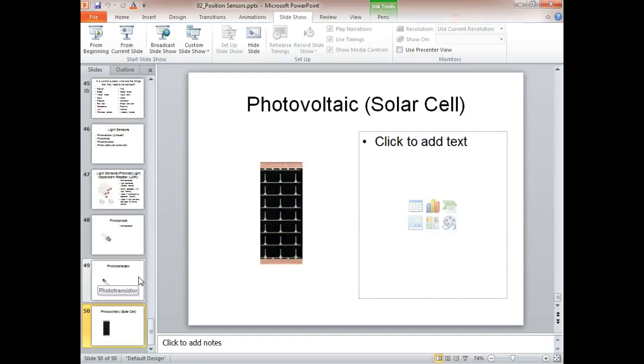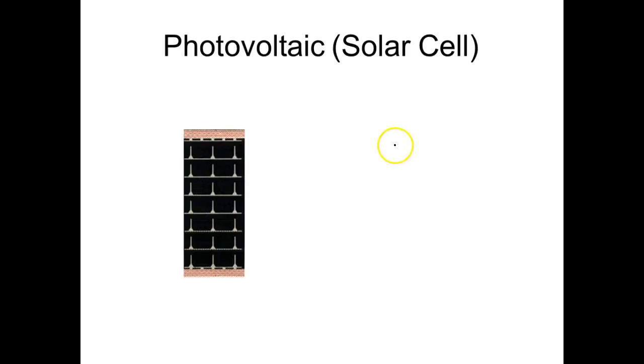So photovoltaic cells, that's the technical name. Most people call them solar. So if I hook batteries in parallel, then what we do is we add the amps together. But you have to hook them in the same direction. If you hook them in opposite directions, they're canceling themselves out, and they'll run down real fast because the other battery acts like a short circuit to the other battery.